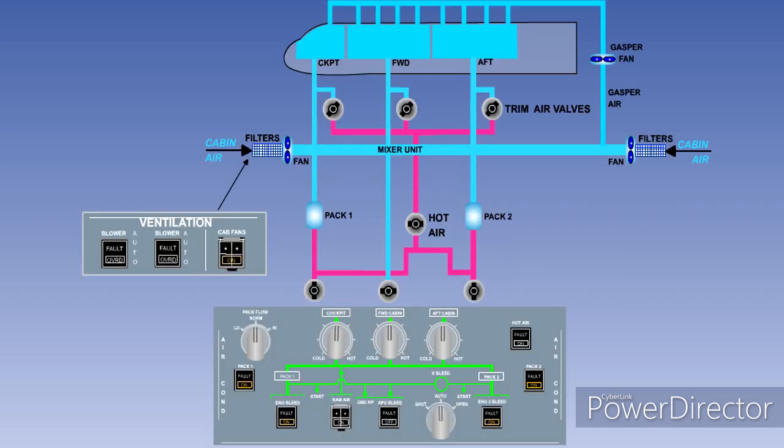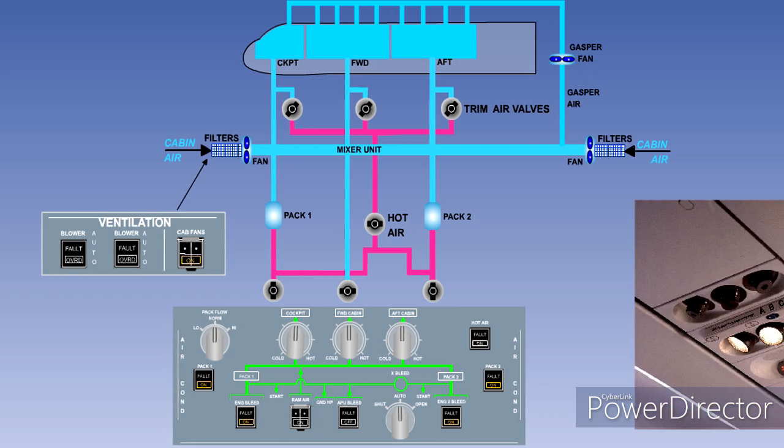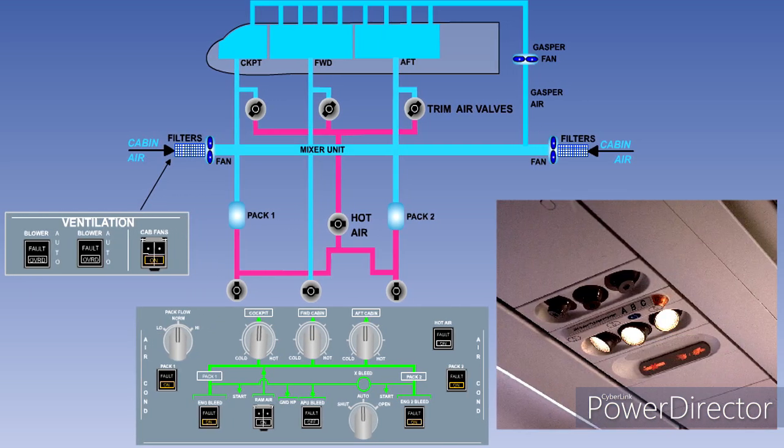The ducting is in two distinct sections, to provide for separate flows of cold and heated air. The cold conditioned air is supplied to the passengers individually, through a system known as the Gasper air system. Gasper air is tapped from one of the zone's supply ducts upstream of where trim air is added. The Gasper fan provides a positive supply of conditioned air to all zones through individually controlled outlets or punkah louvers.